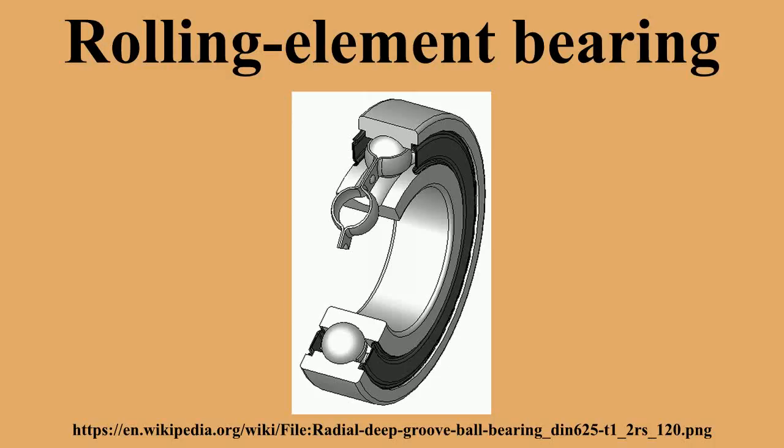The downsides to this bearing is that due to manufacturing complexities, tapered roller bearings are usually more expensive than ball bearings, and additionally under heavy loads the tapered roller is like a wedge, and bearing loads tend to try to eject the roller. The force from the collar which keeps the roller in the bearing adds to bearing friction compared to ball bearings. Needle roller bearings use very long and thin cylinders.